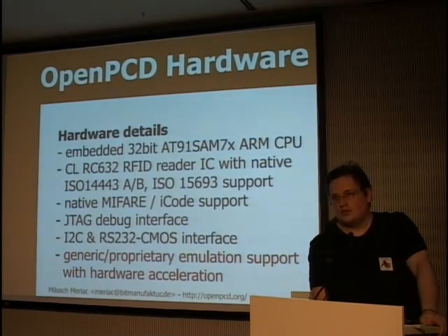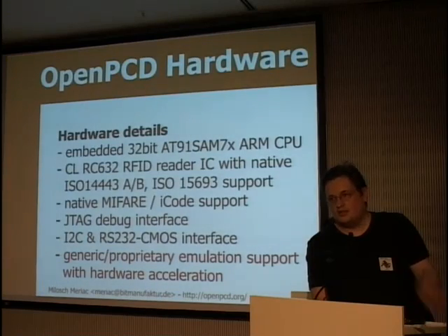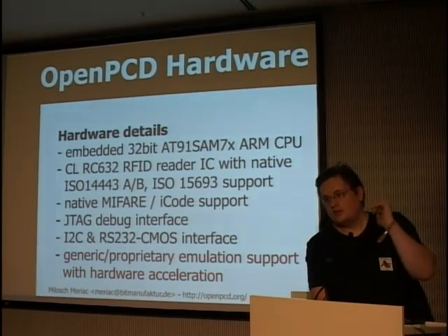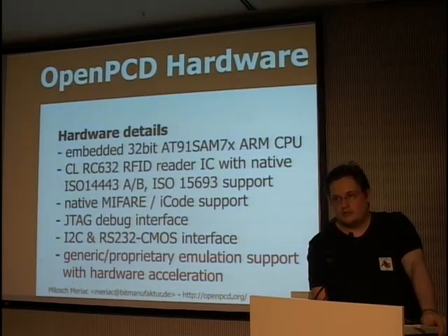So you don't have to do the timing in your software. You can just pre-compute the bit patterns, start a DMA request, and they are constantly clocked out at the baud rate you expect. This solves a lot of problems for you when emulating stuff.